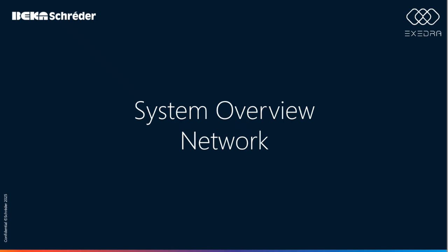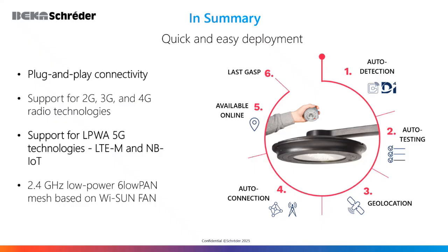And then the last gasp is a very unique feature whereby communication after the loss of power to the node is pushed to the cloud services. So the node has a built-in supercapacitor which gives enough power to the node to communicate its last data instantly when the fault occurs. So a very unique feature of our hardware.